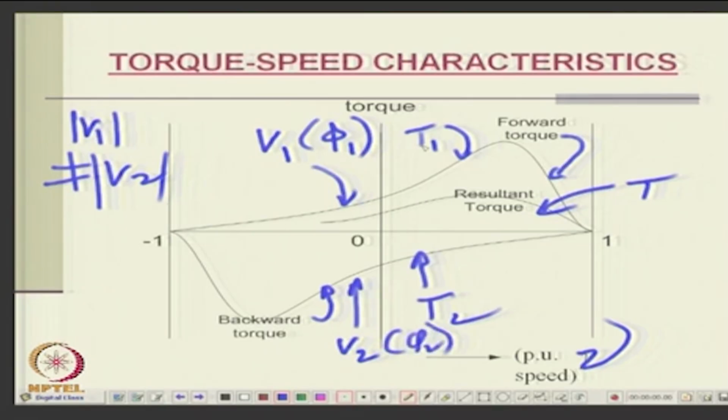And in this analysis, your phi 1 is constant throughout, unlike what we discussed earlier for a single winding machine. Okay. So, this phi 1 is constant so long as the positive sequence voltage is concerned, and phi 2 is constant so long as the negative sequence voltage is concerned, at all speeds. Okay. With this analysis, for a 3-phase machine, because we had taken a balanced machine, our machine is balanced, voltage is unbalanced, therefore this phi 1 is constant and this phi 2 is constant. Any doubt on this basics? So, throughout, your flux per pole is the same at all the speeds.